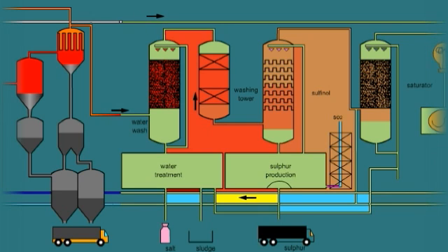During the following desulfurization, toxic H2S, hydrogen sulfide, is removed from the coal gas. More than 99% of the sulfur extracted from the coal is bonded and converted to pure sulfur for reuse by the chemical industry. A very small proportion of the sulfur enters the air as SO2, sulfur dioxide, via the waste gas combustor.